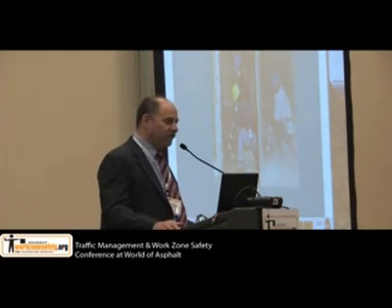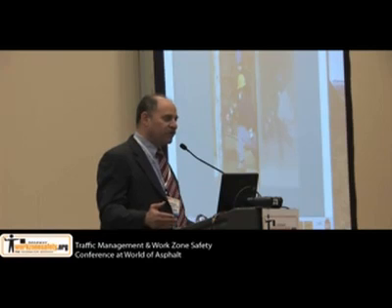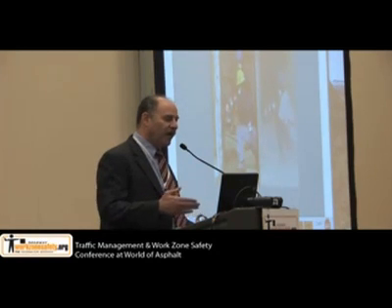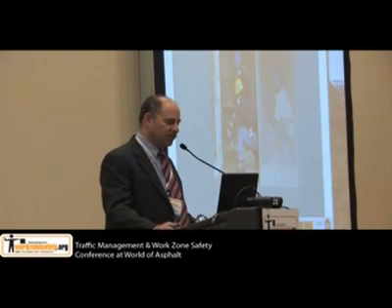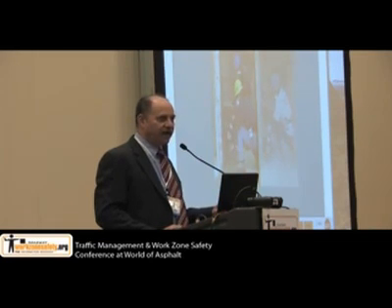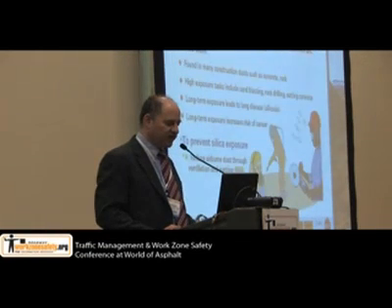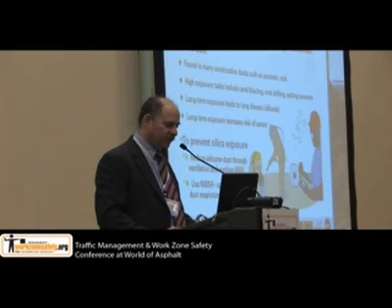And here's a demo we developed where you can see on the right side someone is cutting without using any water. On the left, they're wetting the saw as they're cutting. So you can see there's a huge difference in exposure. And it's likely that OSHA, when they come out with their rule sometime this year, is going to propose that all cutting has to be done with wet methods or with local exhaust ventilation, or you need to use NIOSH-approved toxic dust respirators. And there's the OSHA standard.